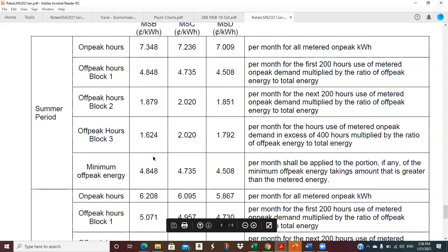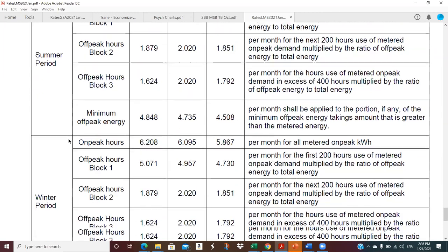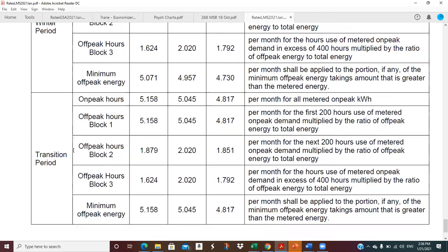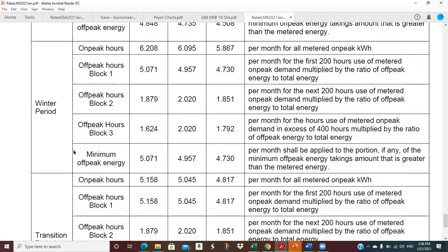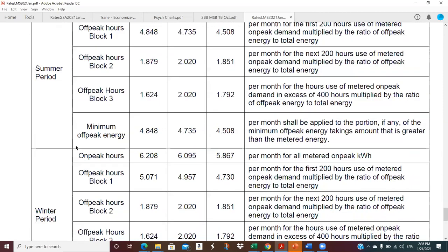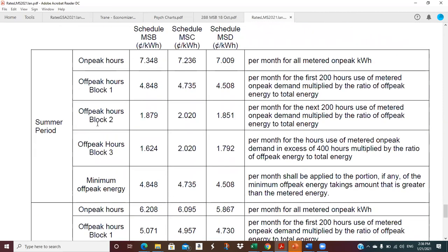Anyway, so we go through this depending on which month we're in. Summer, winter, transition period. So, if you just look at this, you can save some money. For example, at Florham, they had some big ball mills, like 900 kW ball mills. And they were running them on peak. And their production was not full. If they were full production, they'd run them all the time.